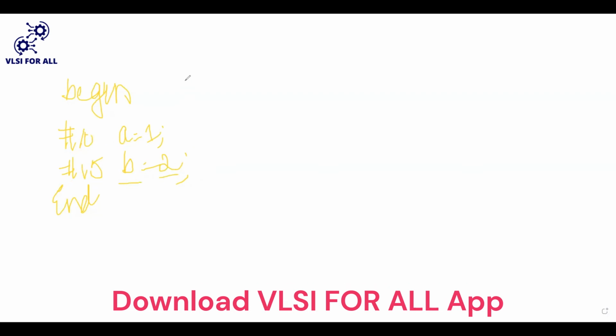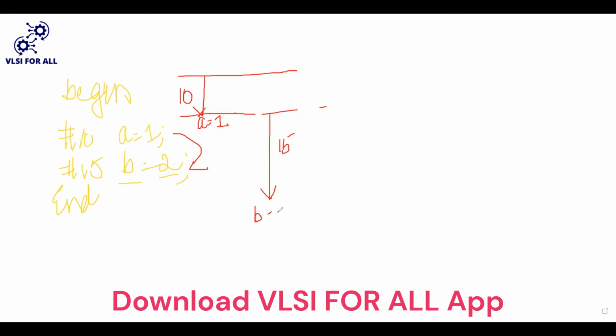So here what will happen is, whenever the begin statement is started, in between the begin and the end, first when the execution starts at the begin, after 10 nanoseconds the value of A is assigned with 1. Once the value of A is assigned with 1, after this, at 15 nanoseconds, the value of B is assigned. Now the fork and the join. Let me consider the same statements.